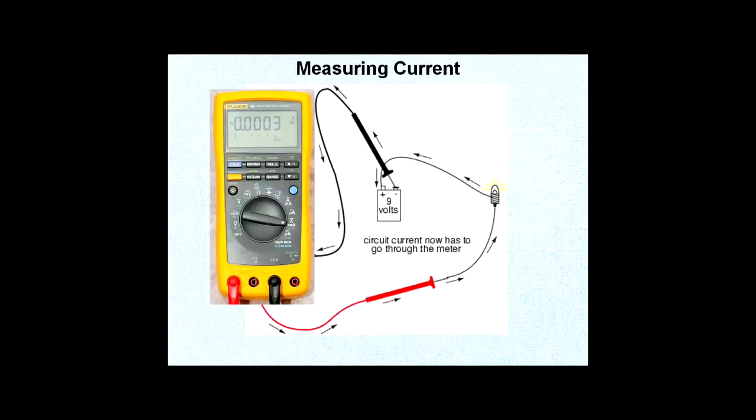Measuring current. If you do the same thing as we did with the voltmeter, connecting the probes straight to the 9-volt battery, because the ammeter has almost 0 resistance, then the current is just like shorting these two terminals together. We're going to have extremely high current flowing from one terminal to another because there is nothing to slow the current down. So if we connect anything, let's say this is a light bulb or a resistor, that's something that poses a certain type of resistance just to slow the current down, then we can measure the current by connecting this ammeter in series. Let's analyze the circuit.